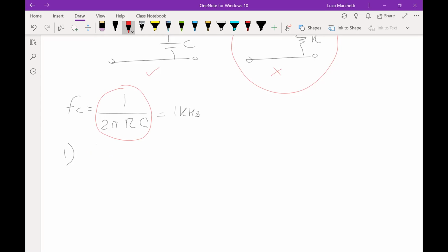So it means that the denominator will have a unit around millisecond, because the opposite of a kilohertz is millisecond. And this means that the product between the resistance and the capacitance should be millisecond. So I can create milli by doing, for example, kilo and micro, because the product between kilo and micro is milli, okay? So I can think about a capacitance of microfarad.